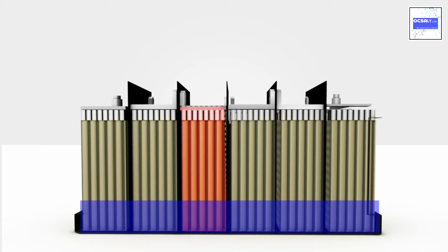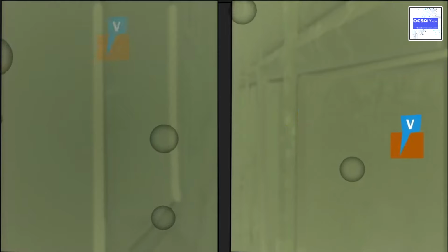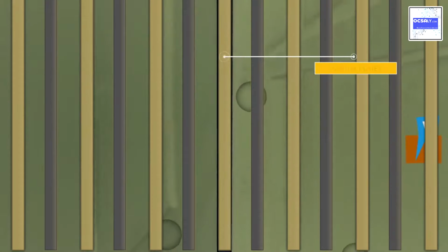A vehicle 12-volt battery is made up from 6 cells. Each lead-acid cell has a nominal voltage of 2.1 volts, which gives a value of 12.6 volts for a fully charged battery under no-load condition. The 6 cells are connected in series internally in the battery with lead bars. The cells are formed in the battery case and are completely separate from each other.